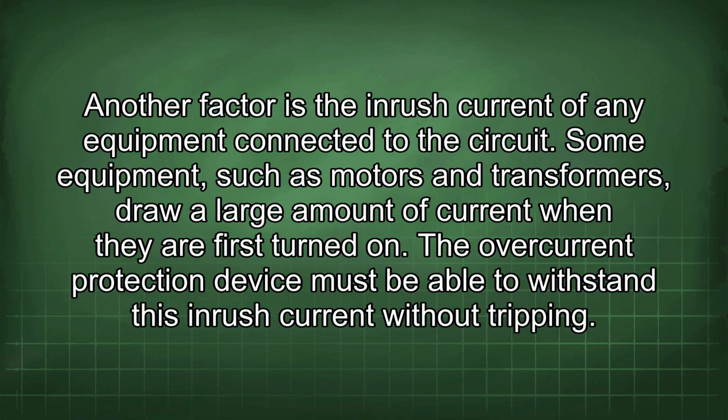Another factor is the inrush current of any equipment connected to the circuit. Some equipment, such as motors and transformers, draw a large amount of current when they are first turned on. The overcurrent protection device must be able to withstand this inrush current without tripping.